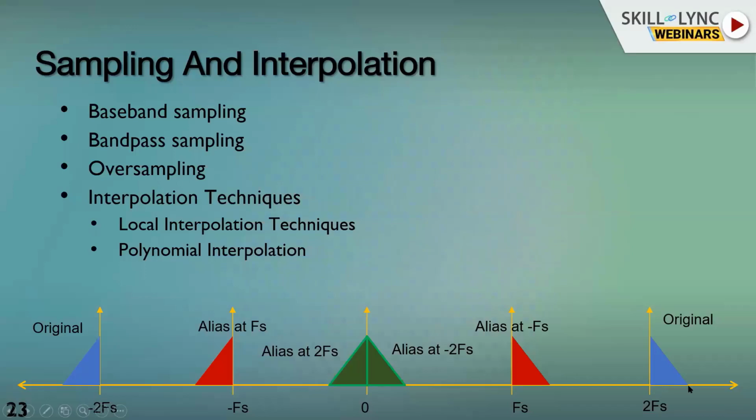So here, if this is the maximum frequency component, then we will choose double of this frequency as the sampling frequency. This will not be desirable in many applications. Like I have shown here, the maximum frequency component can be too high, and to have a system which is operating at that high sampling frequency is very expensive. The clock which is running that system can be very expensive.